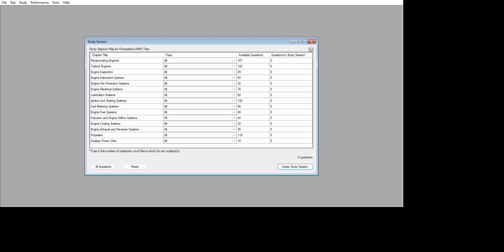When preparing a propeller blade for inspection, it should be cleaned with mild soap and water. The aircraft propeller system beta range is used to produce zero or negative thrust. Magneto breaker points must be timed to open when the greatest magnetic field stress exists in the magnetic circuit.